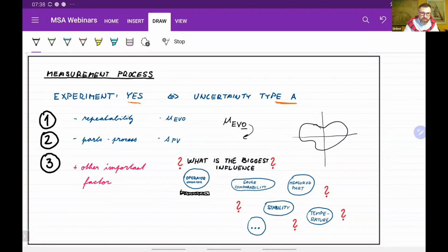So what is the diameter of a circle like that? It can be anything between this and this, and it really depends on the definition of the measured parameter. And since any measured parameter is burdened by its shape, then no matter what the definition is, there can be a variation coming in with the part. Of course, there are ways to limit that to a certain point, like calculating the average diameter. But if we care about the max-min, it usually is a big factor, a thing to consider.